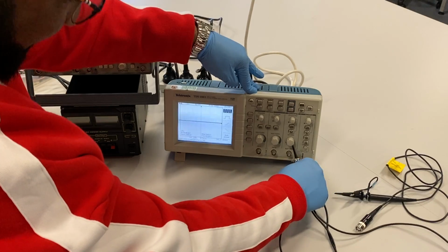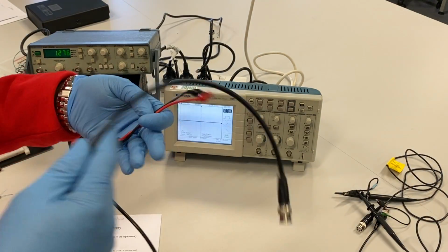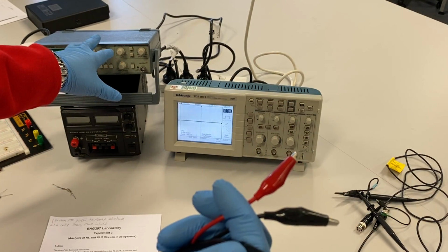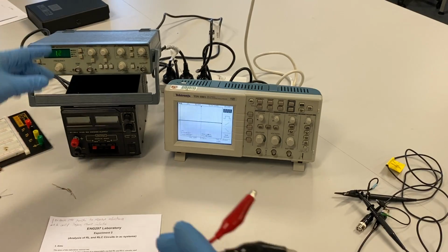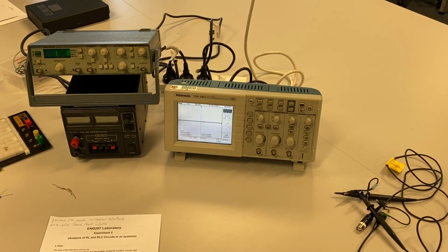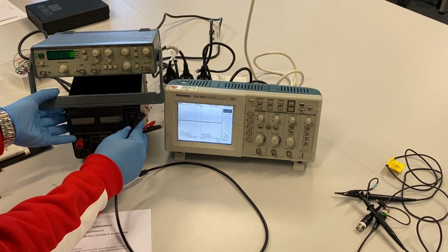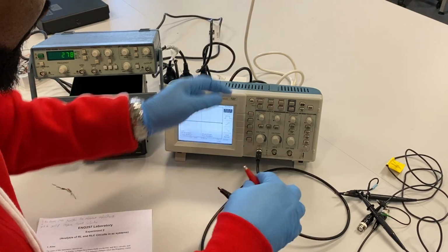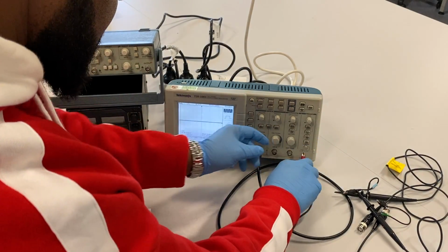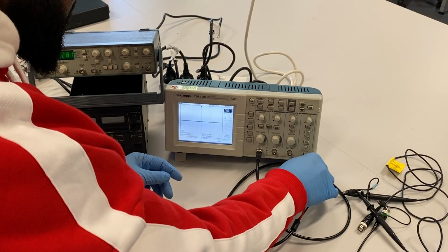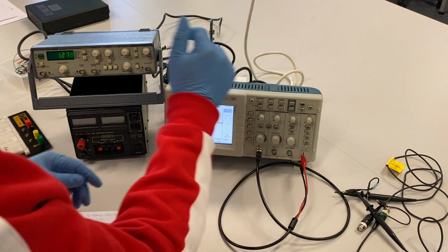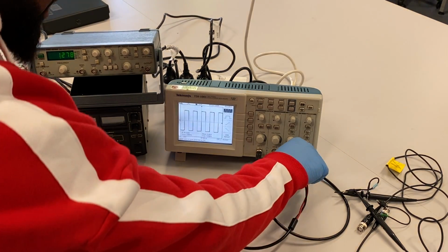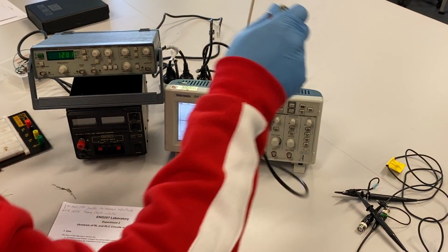So these two oscilloscope cables are working, but we need to check also the BNC probe, because this is the probe that will transfer our signal from the function generator. If it's not working, then we are going to suffer. So let's check it out. Connect it to any channel, just like those cables. Connect positive to positive and ground to ground, and we auto set. Exactly, we get a square wave. So it means all our cables are working for now. That's very good.